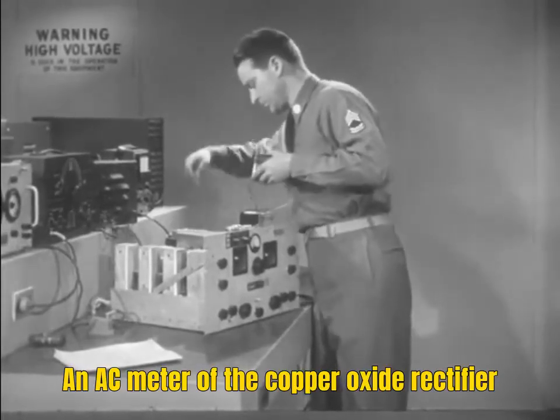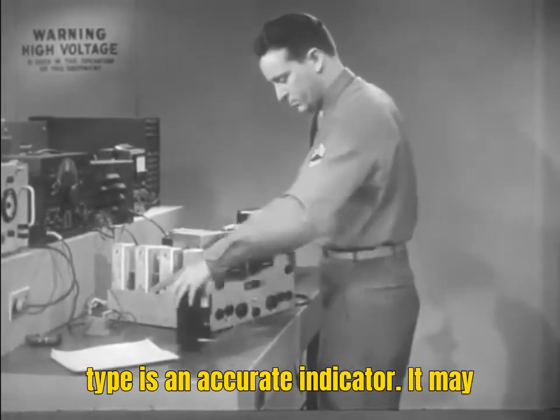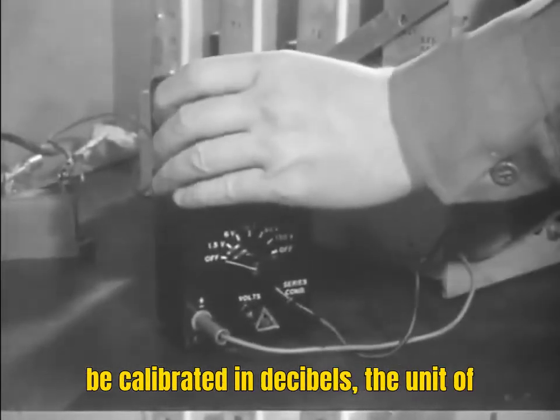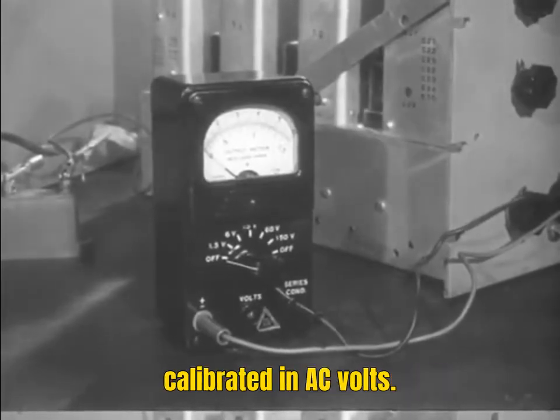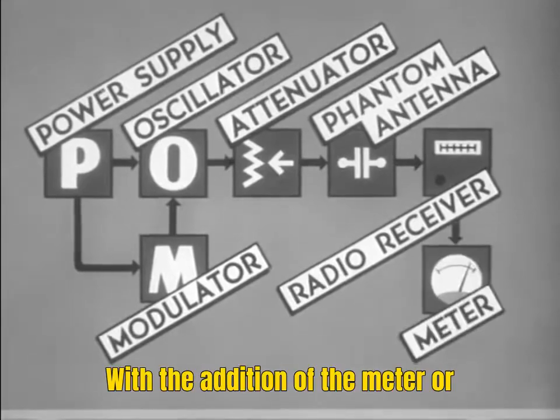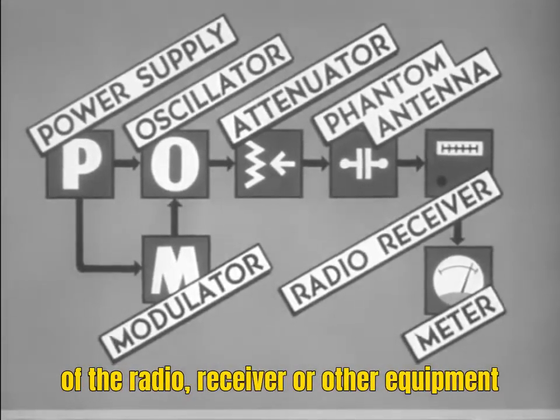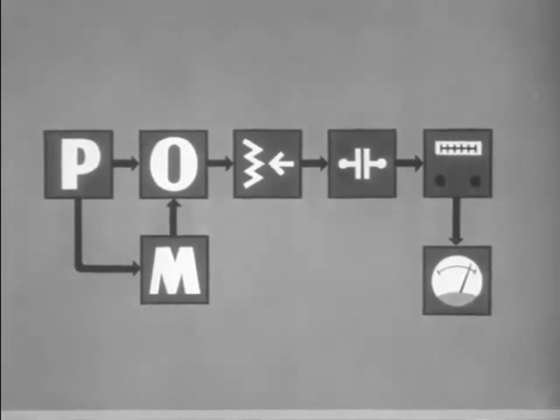An AC meter of the copper oxide rectifier type is an accurate indicator. It may be calibrated in decibels, the unit of sound power, or it may simply be calibrated in AC volts. With the addition of the meter or indicating device connected to the output of the radio receiver or other equipment under test, the circuit is complete.